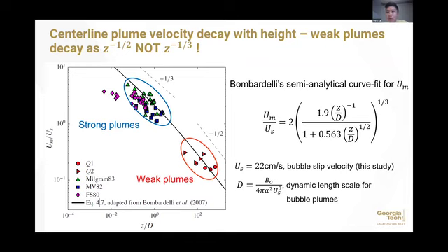He worked with the governing equations, made the entrainment hypothesis, and then solved the equations. But the prediction of the centerline velocity decay actually predicted that for large Z over D, you do have this -1/2 scaling. That was quite interesting, because this shouldn't have been predicted by the entrainment hypothesis.